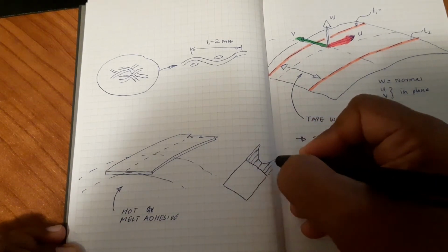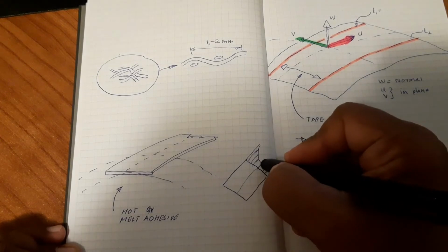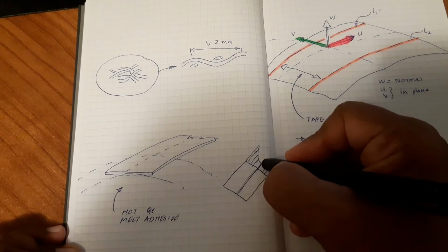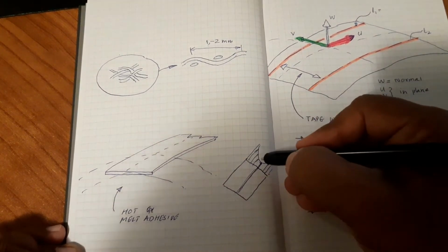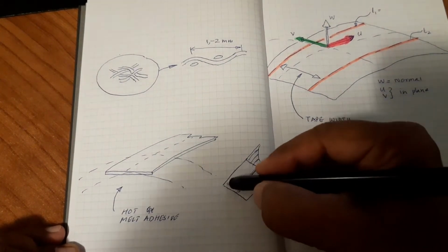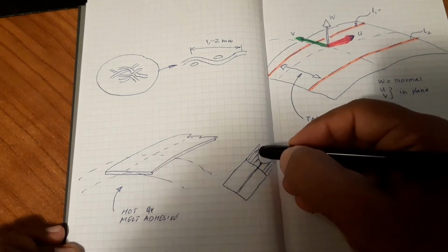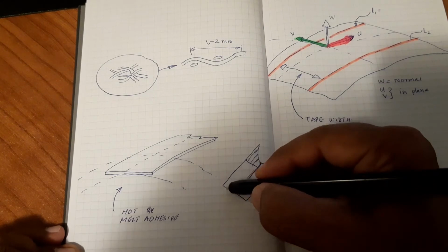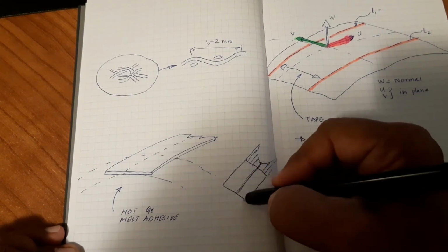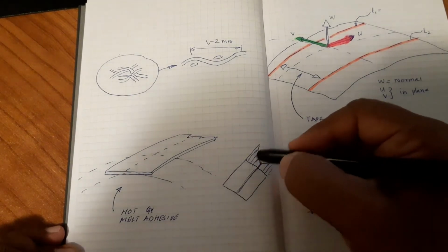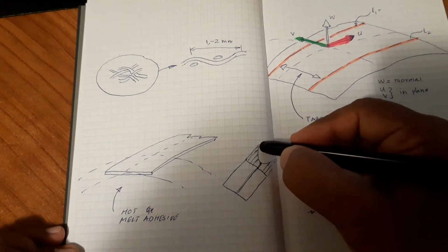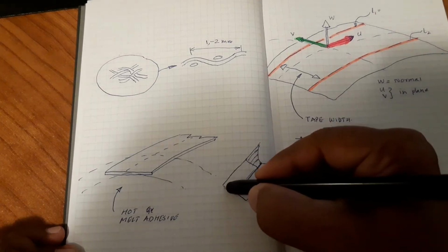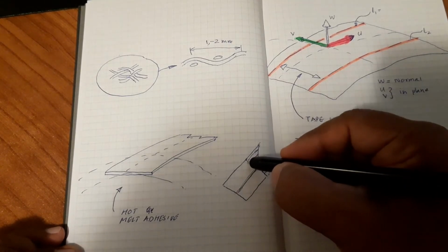So this should be the amount of stretch. That means the ATL machine is following this curve on the mold, and if it is curved convex, and you started off like this with a rectangular end over here, at this end you will have to stretch this fiber more, because the length at the bottom is smaller.